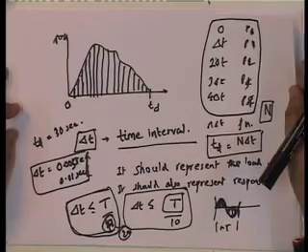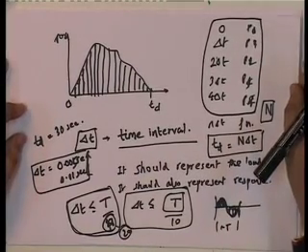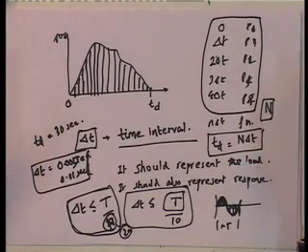For example, let us say that a measuring data acquisition system has a maximum of 200 samples per second. What does that mean? It means essentially delta t is 0.005, because you are getting 200 samples per second. So, delta t is automatically set.